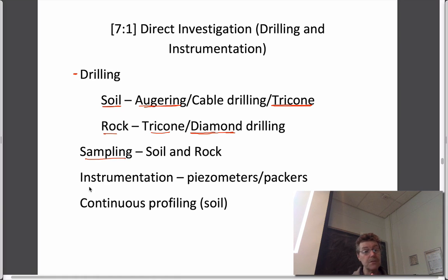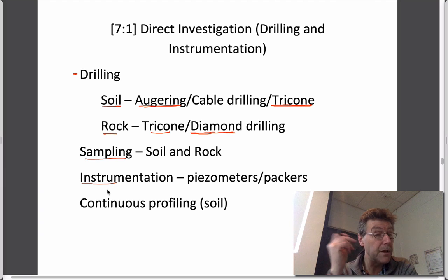Maybe you want to leave some instrumentation in it to be able to measure things like contaminant concentrations and pressures, and be able to use that instrumentation to do well tests to measure permeabilities, which you can then link to capillary entry pressures, etc. And so it's useful to be able to get the most from these boreholes. Typically, when you go off a hole, you want to seal it if you're not casing it, because you don't want to cross-contaminate aquifers, and you're almost usually required to do that. And so we'll talk about those methods today.